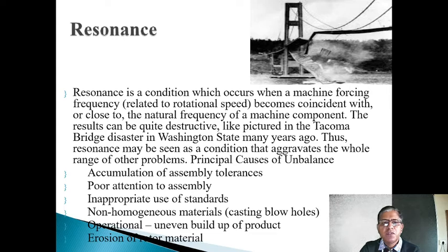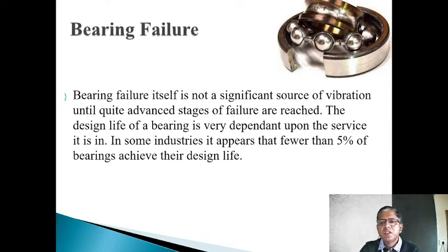The principal causes of resonance are the matching of excitation frequency with the natural frequency. Then comes the bearing failures. Bearing failure itself is not a significant source of vibration until quite advanced stages of failure are reached. Unless there is some problem in the bearing, it doesn't generate vibrations. But if the problem persists in the bearing, then it gives indication in the form of vibrations.